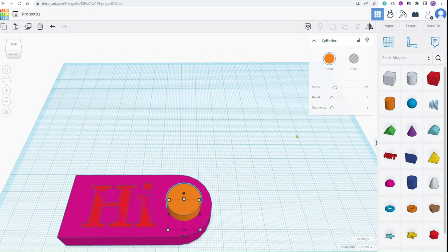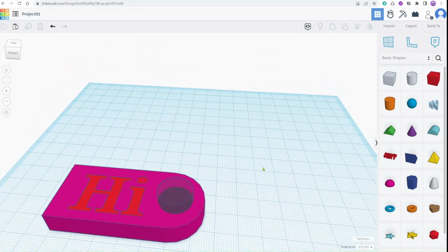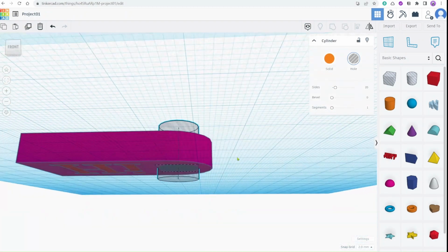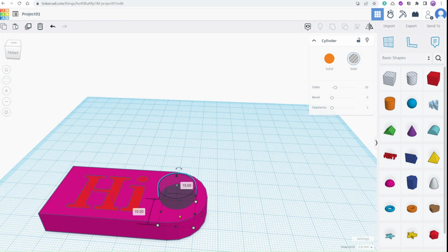So click this, and then we change its property from solid object to hole object. What it does, hole is kind of a cutter. Solid object, that's a solid piece. But hole object is not solid. It's kind of a knife to cut or engrave. Since this is a cylinder object that is a hole, and that goes through all the way down here, right? So when I apply its function, that's gonna cut out this way as a cylinder, as a hole, right?